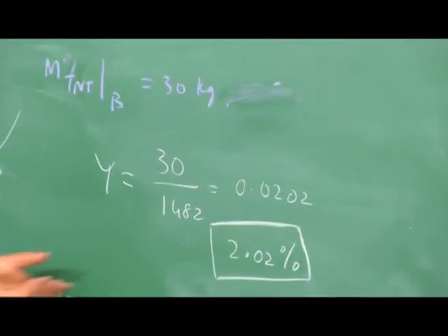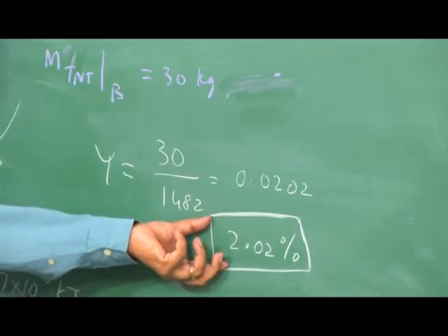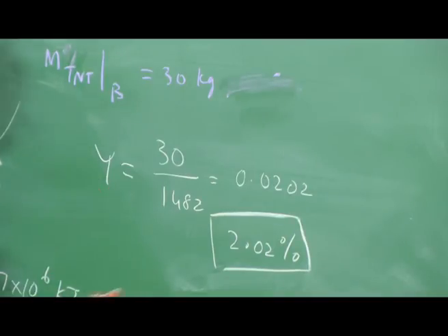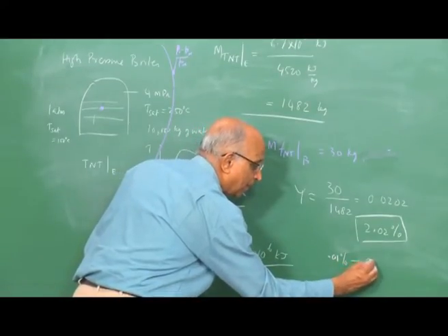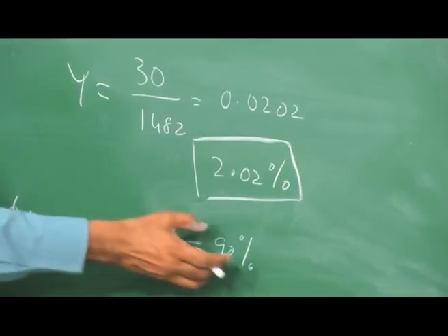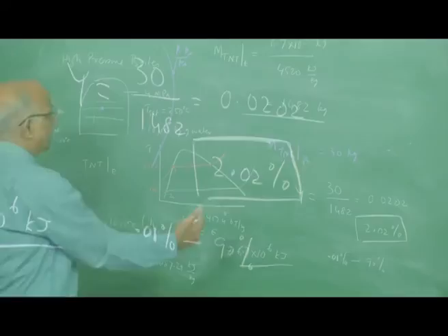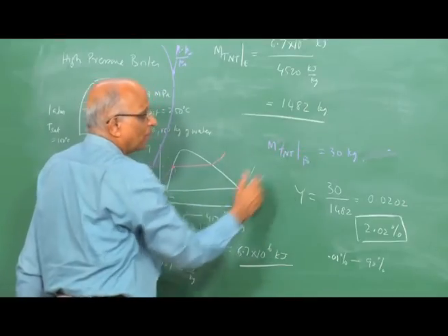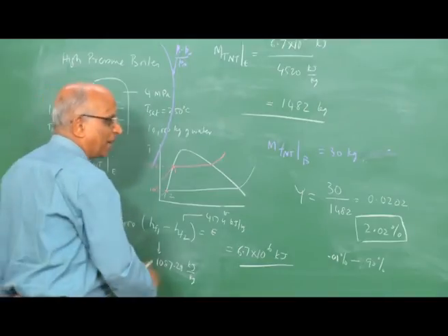In practice, whenever we have dust explosions or vapor cloud explosions, confined, unconfined, or any other form of explosion, the yield changes enormously. The yield could be as low as 0.1% to as high as maybe 90%, or when I use very powerful solid explosives, the yield could even be greater than 100%. This is the way we calculate the yield, the TNT equivalence for the energy basis, and the TNT equivalence for the blast basis. Let us do one last problem such that we are absolutely clear.